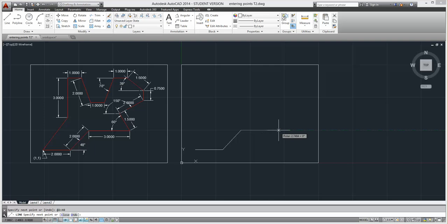Now it says that I want to do a relative coordinate. So I want to go to the right 3 inches. Now I have to do another line that's going to be at an angle. So I have to do, at that point, the line length is 1.5 inches with an angle that's unknown. You're going to have to do some math here. This is your origin.